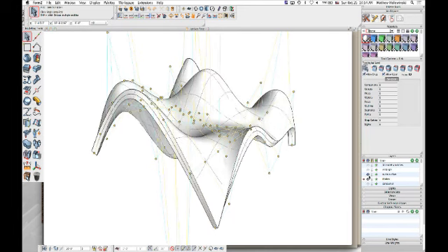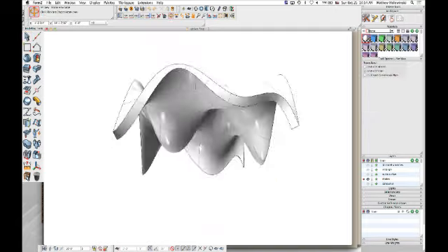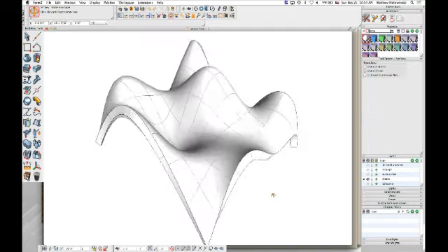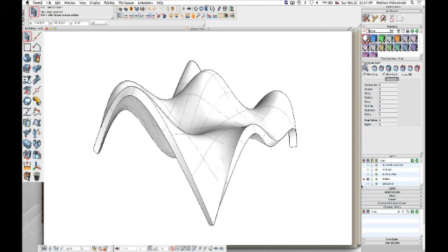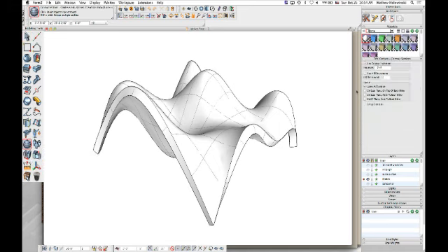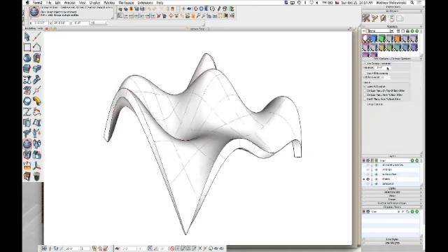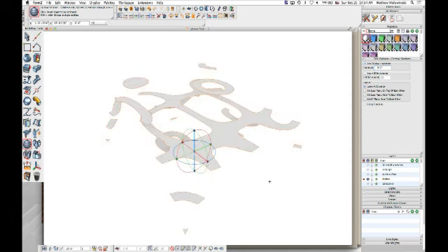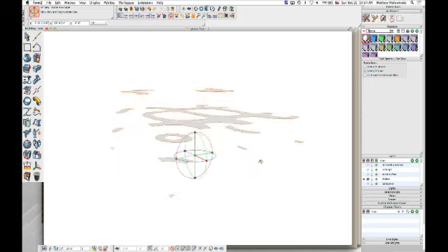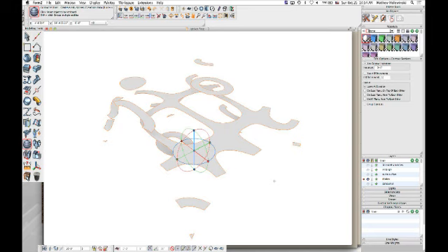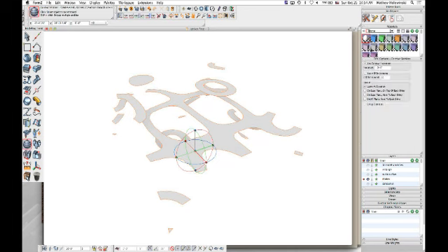We can use the thicken tool to give it whatever thickness we want, right? And then we can cut a series of contours. There's an actual contour cut tool. And if I were to click on that object, let's cut it every 6 inches. I click on it, and there, we cut cross sections every 6 inches. Once again, result buffer mode, live dynamic editing of those contour cut parameters. So I can change the distance maybe from 6 to 3. So now I'll have more cuts through there.